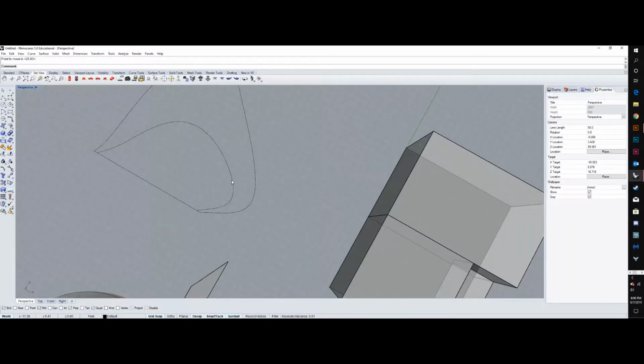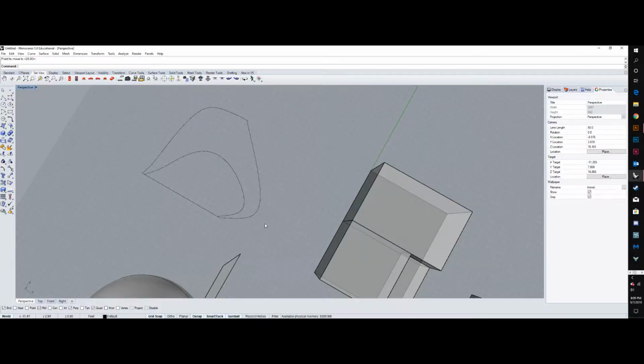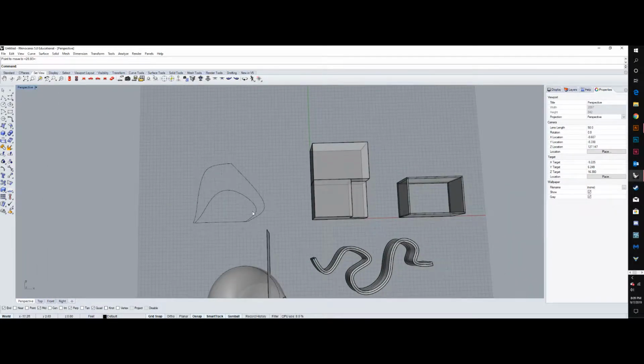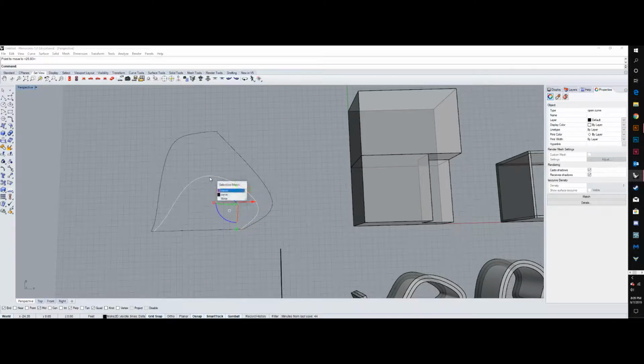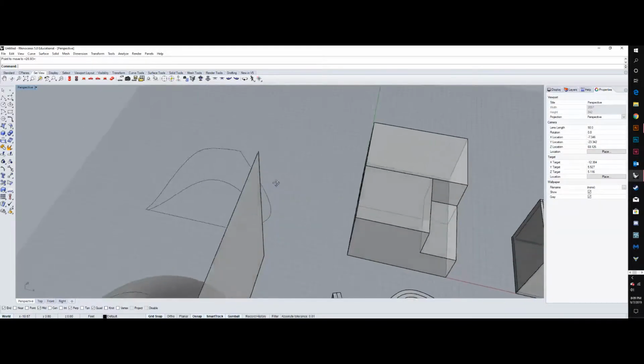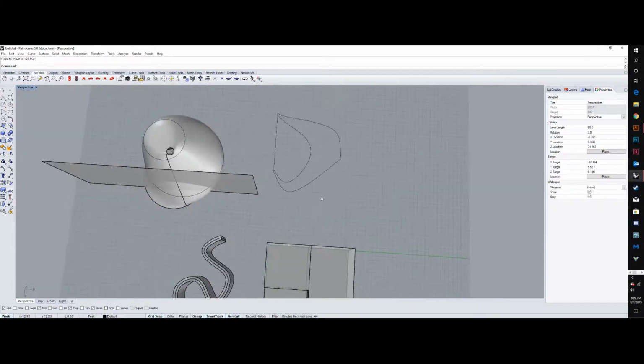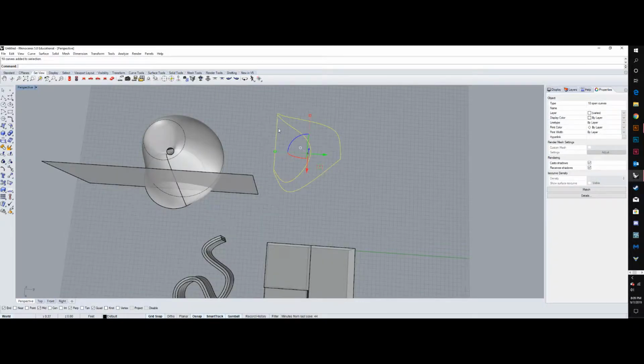So now I have two lines here. I have a purple line, which in context of moving this drawing to Illustrator, I will know that my purple will be for cut lines. And I have the actual lines from the Make 2D, which Make 2D will always split curves up into many, many lines. In this instance, it's just 2 lines, but sometimes it's several little line segments. But I digress. So if I wanted to move this into Illustrator, I would select all of this.